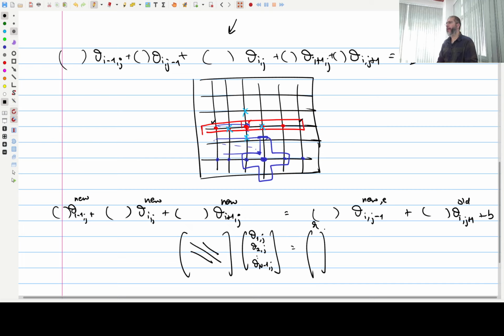Now what is the benefit? The benefit is the speed with which the boundary information gets diffused is much faster. Because think about it, ultimately this equation is simply diffusing the boundary value into the domain. There is nothing being generated right now. Although the equation could have more terms, the way we have written it, we are solving this particular kind called the parabolic equation, the heat conduction equation. So here what's happening is the boundary information is diffusing into the domain. The faster it happens, the better it is for us.